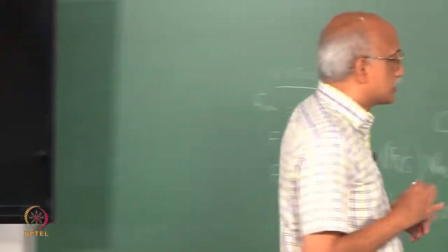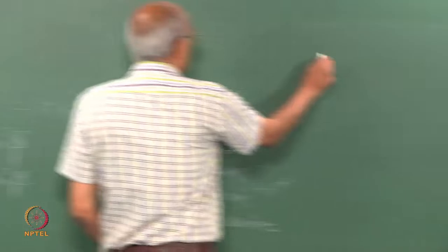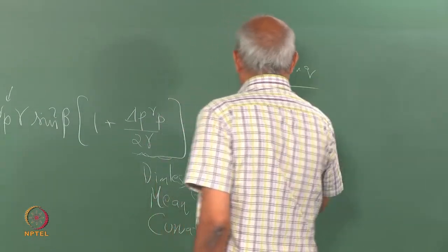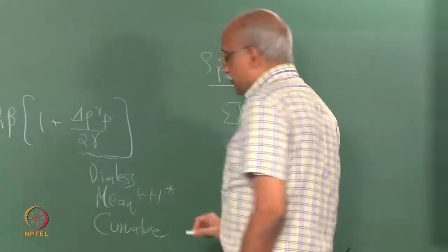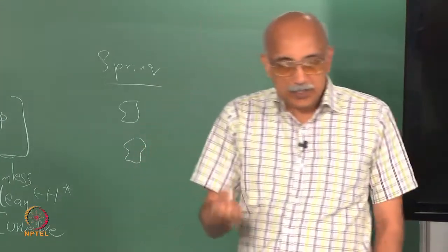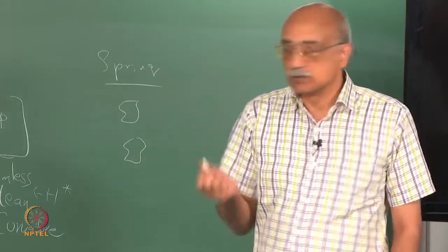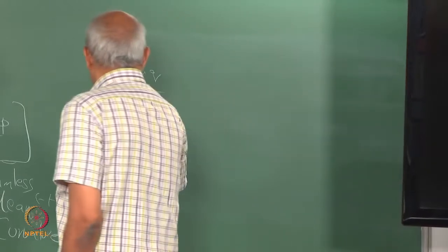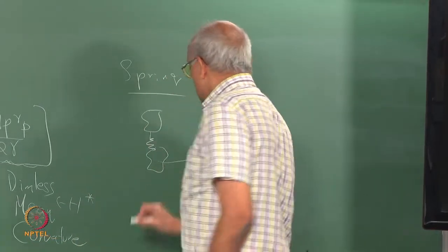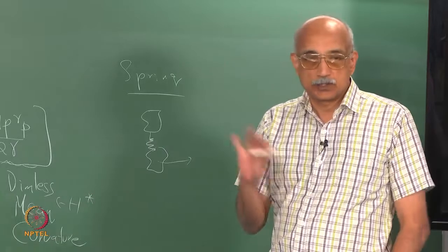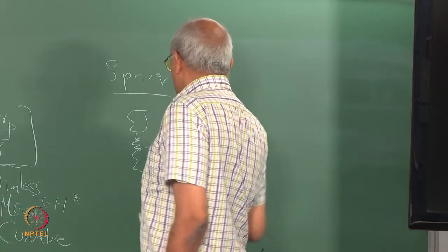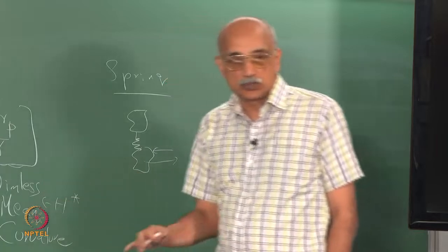The third type of force is the spring-like force, and this refers to the fact that when you have two particles that are suspended, they almost behave like they are connected by a spring. As one of the particles drifts away with a relative tangential velocity, there is also a tendency to bring the particle back to its original location.